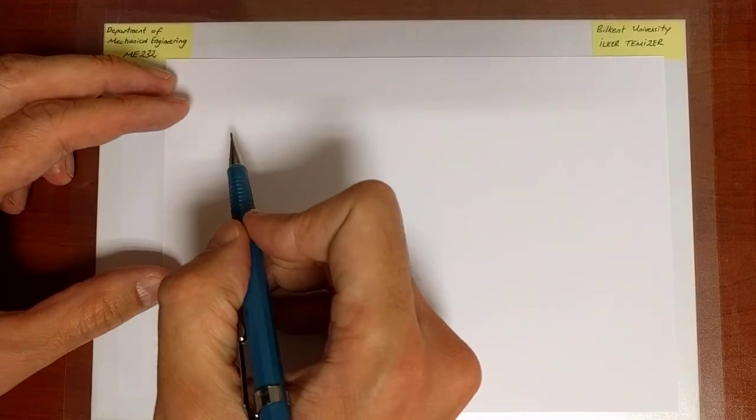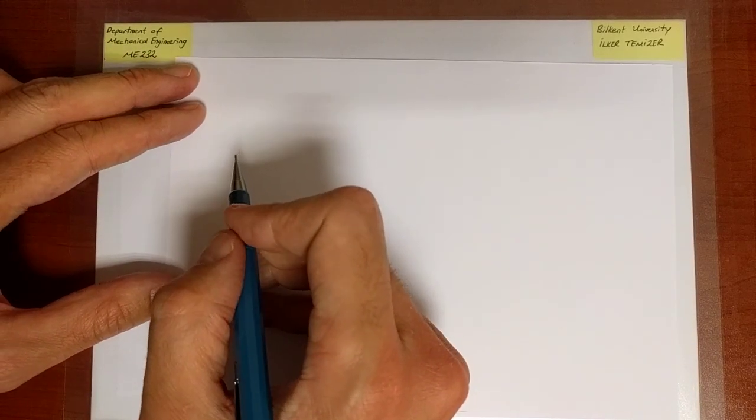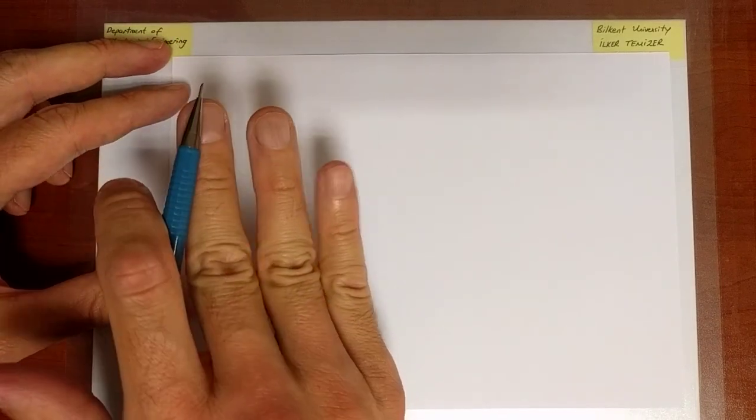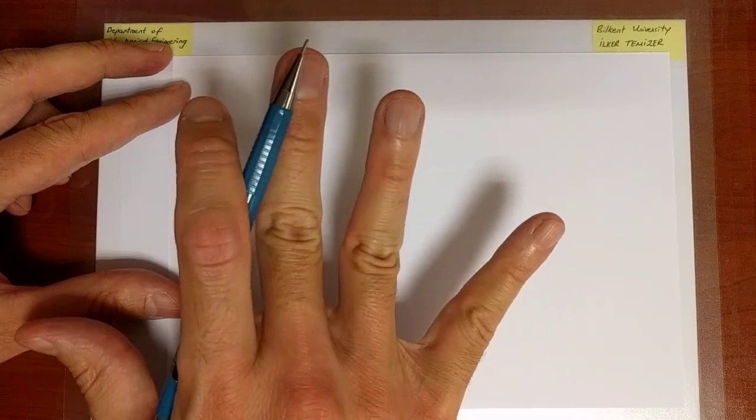All right, so now we do understand a lot more than we used to about the stress-strain curve. In particular, we've introduced the true and engineering stress-strain curves. Now, in the homeworks, you are going to employ both of them. What you should remember at this stage is that if the deformations are small, in other words, if the strains are small, there is no distinction between true or engineering stress or true and engineering strain. They are approximately the same.